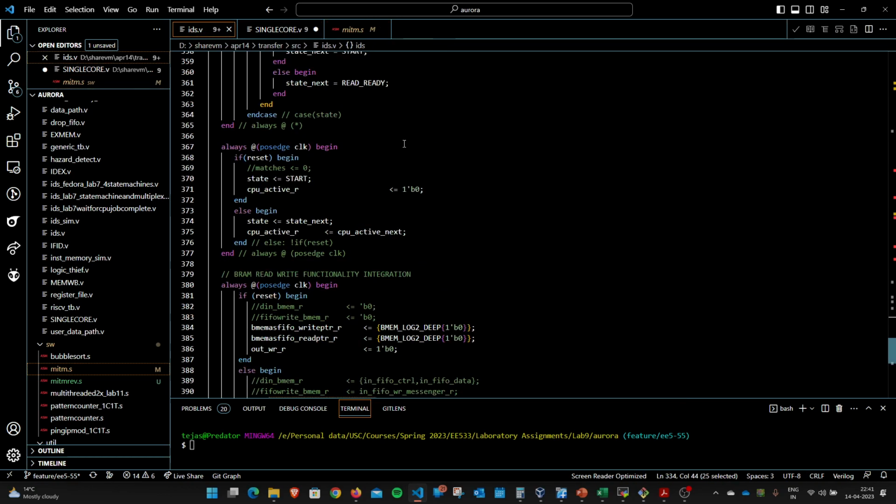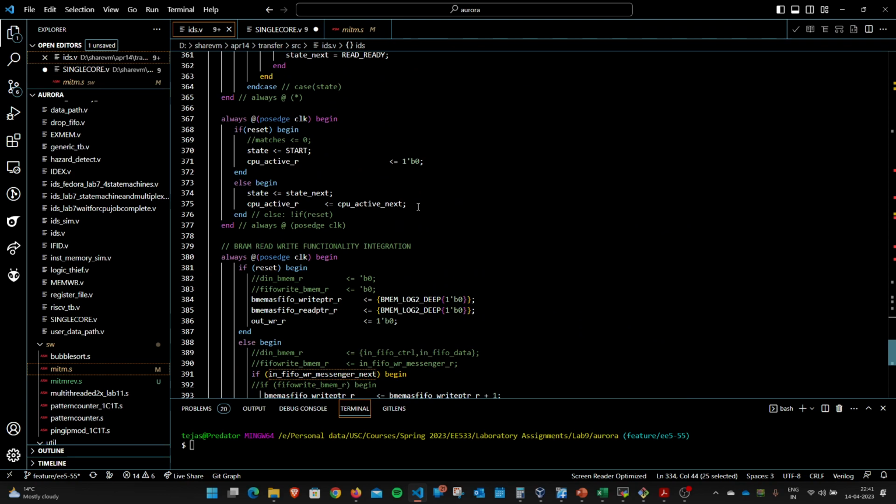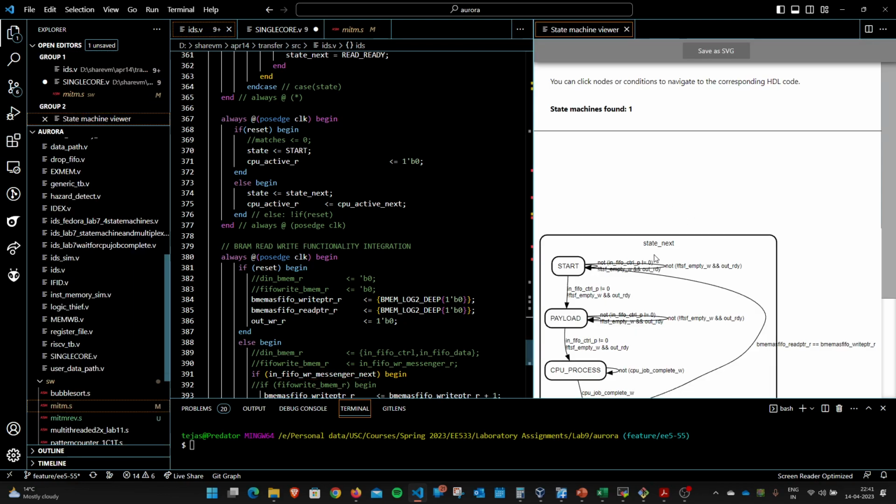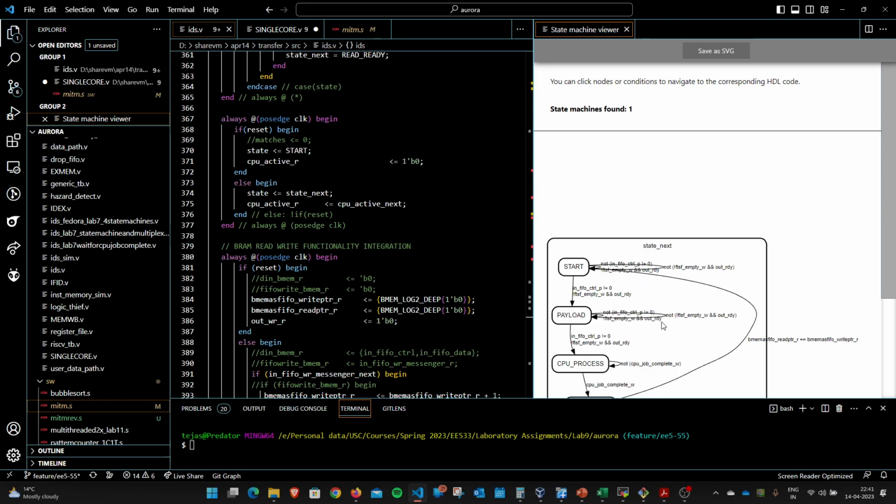But before this, I would like to show you what our protocol is. We have implemented an intercommunication between the threads. Here you have our FSM, and it governs the exchange of data between the NetFPGA and our code, and that's how they take turns to access the data memory.